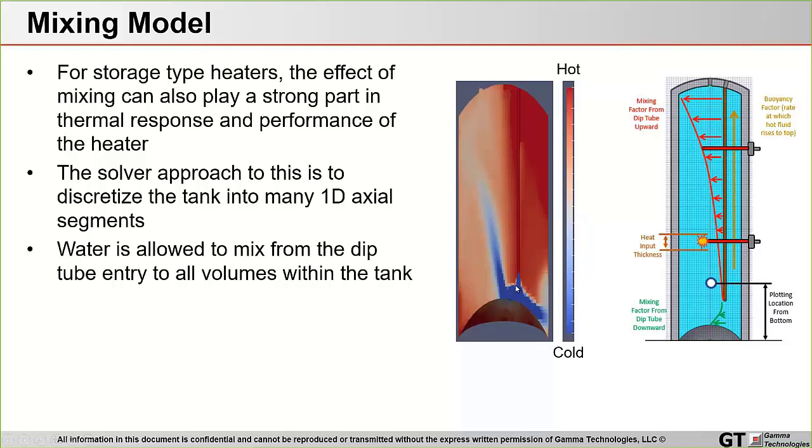And by having this nice flow path from the inlet to the outlet, this encourages mixing of cold water throughout the tank. And so it's not just a simple plug flow model where you have cold water on the bottom that eventually rises to the top. There's actually mixing that's going on in a transient manner.